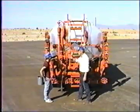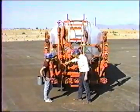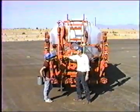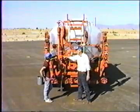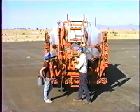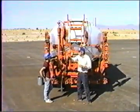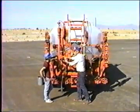But you don't pull a liquid. The only thing that you create when you pump away from here, you've created a vacuum, and in pressure terms, that vacuum or the suction that you've created there has created about 15 psi or 17 psi of pressure pushing that asphalt through that hose.